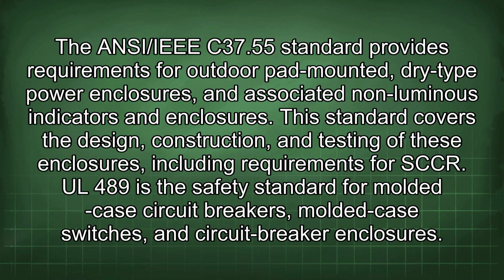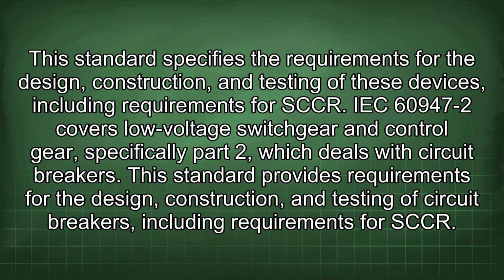The ANSI/IEEE C37.55 standard provides requirements for outdoor pad-mounted, dry-type power enclosures and associated non-luminous indicators and enclosures. This standard covers the design, construction, and testing of these enclosures, including requirements for SCCR. UL 489 is the safety standard for molded case circuit breakers, molded case switches, and circuit breaker enclosures. This standard specifies the requirements for the design, construction, and testing of these devices, including requirements for SCCR.